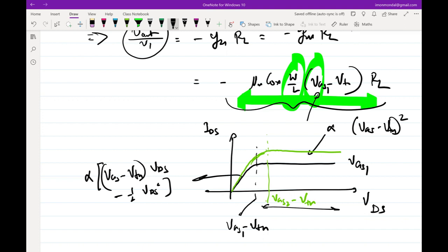It's generally fixed, which means that the maximum VDS or maximum VGS that you can apply is some VDD, right? Which means you are limited. You cannot go beyond VDD, right? This is a system level constraint. We are adding constraint on constraint, right? This is what a designer's job is, to understand what the constraints are.